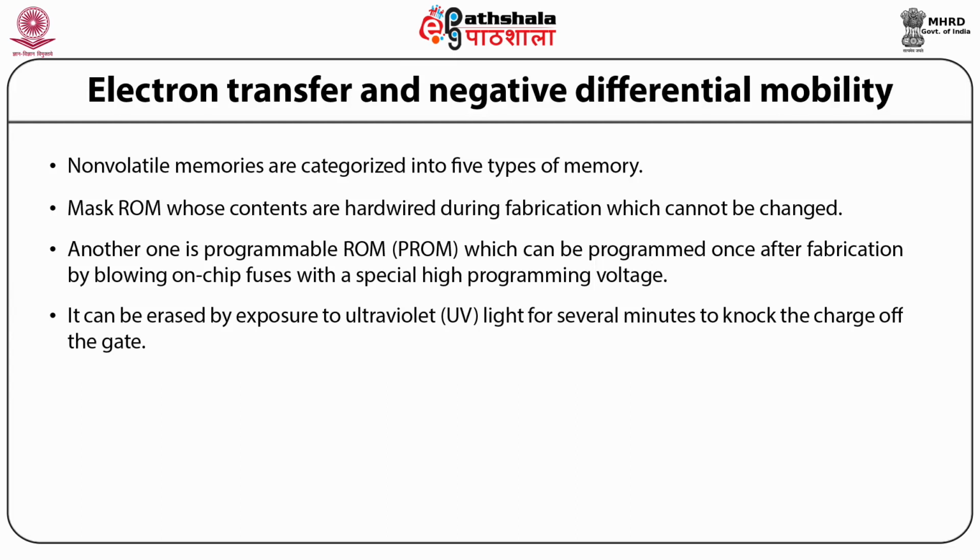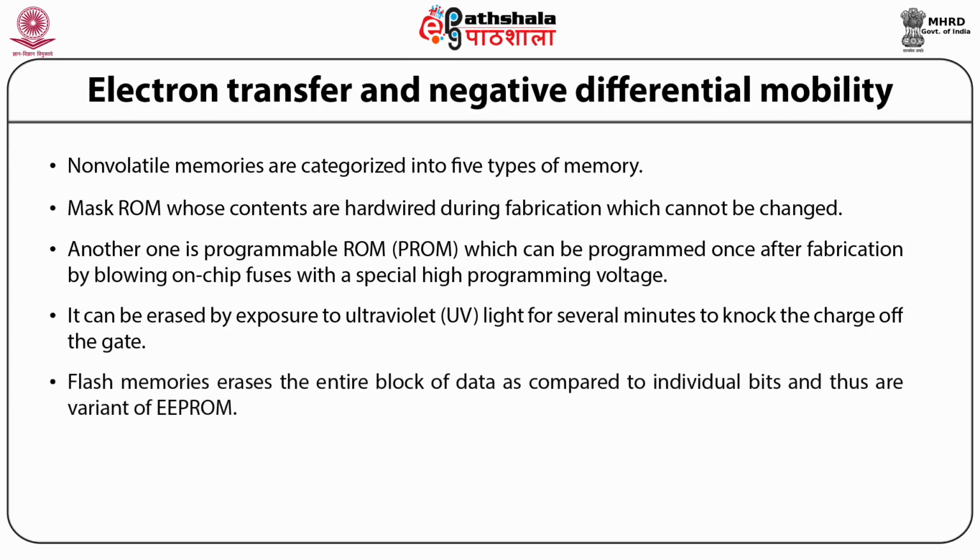charge off the gate. The electrically erasable PROM, or EEPROMs, are similar to EPROMs but the data can be erased in microseconds with the help of on-chip circuitry. Flash memories erase the entire block of data as compared to individual bits and thus are a variant of EEPROM.